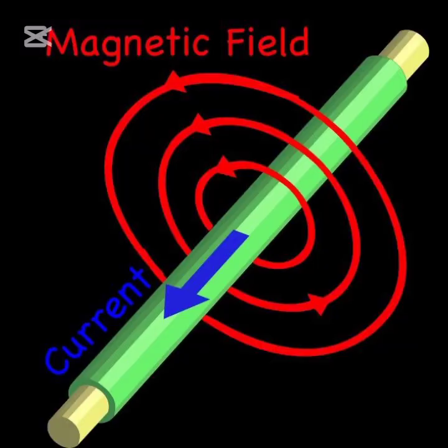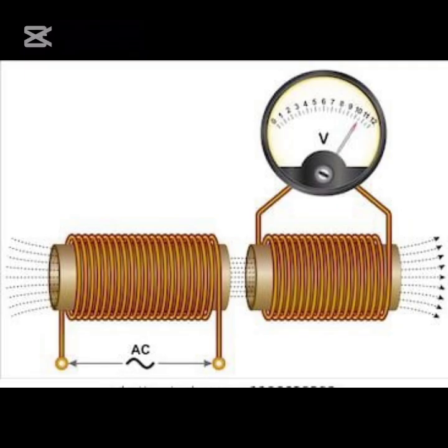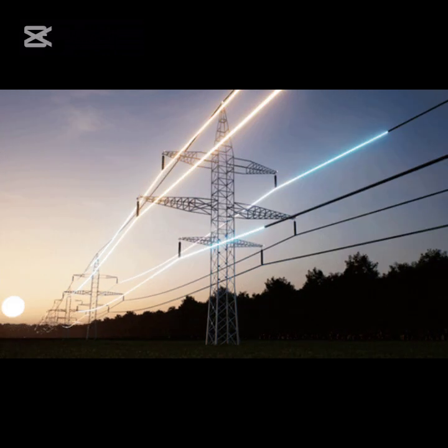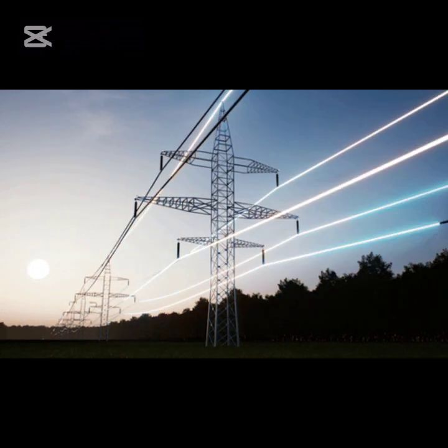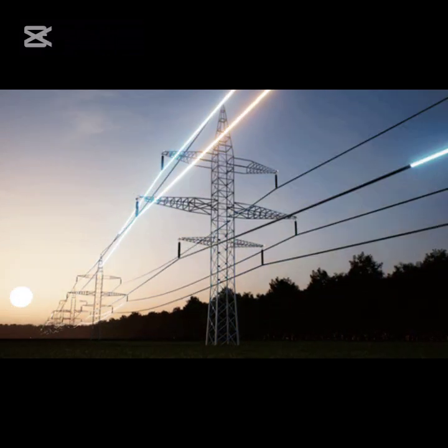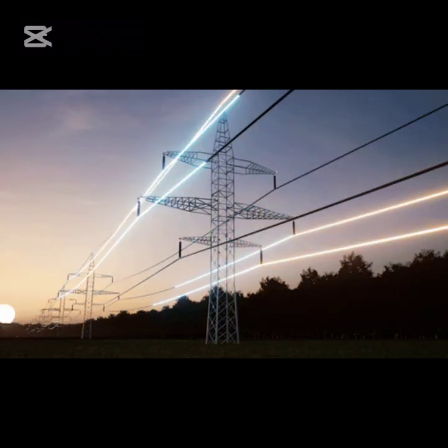The external flux is produced around the conductor due to its own current, and the current of the other conductors placed around it. Note that external flux due to current of the other conductors placed around it is called mutual inductance. It's important to know that the total inductance of a transmission line is directly proportional to its length, meaning it increases as the line gets longer.